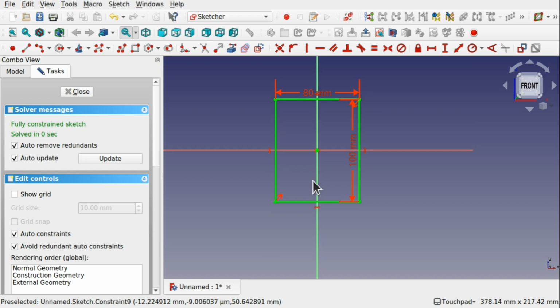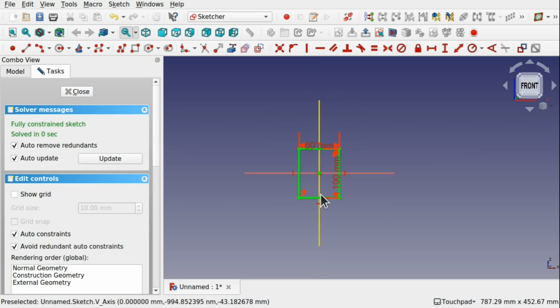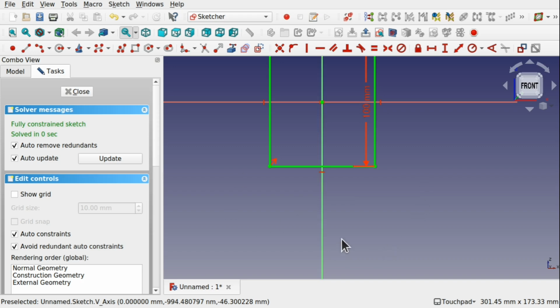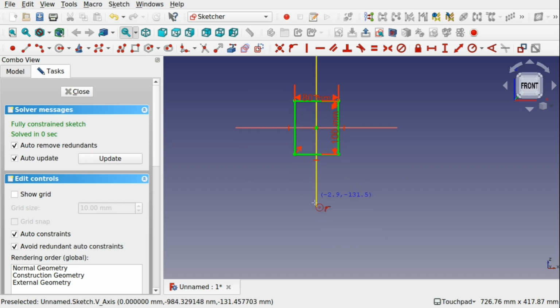Now we've got that, we need to create an arc to allow the crankshaft to sit inside the piston, saving space when this is at full retraction. So when our crankshaft has moved, it's pulled the piston down, then it needs to be embedded in here. So we've got to cut some space out. For that, I'm going to sketch the crankshaft to get an idea of how that's positioned there. That's just going to be a circle. So we're looking at simple shapes to start with. So just place a circle on here.